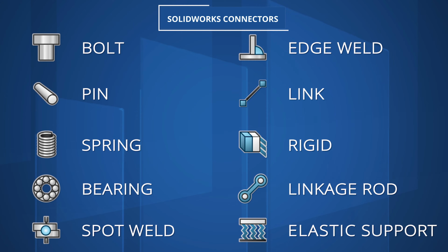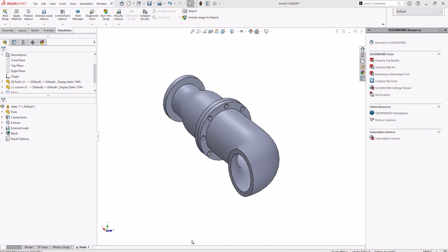These items are simply a representation within the model and don't have their own fastenings, but more importantly, they do not require meshing. This has the potential to reduce your overall element number for your mesh, meaning a more efficient and quicker study. When using connectors, you need to ensure that you're making the right selections for your study.